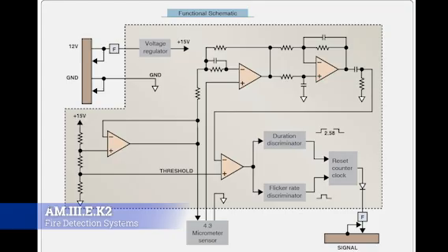Okay, so another type of spot detector is going to be your optical sensor, sometimes called a flame sensor. Essentially, all that is happening is that radiation emitted by fire crosses the airspace between the fire and the detector and impinges on the detector's front-facing window. The window allows a broad spectrum of radiation to pass into the detector, where it impinges on the face of the sensing device filter. The filter allows only radiation in a tight wave band centered around 4.3 micrometers in the IR to pass onto the radiation sensitive surface of the sensing device.